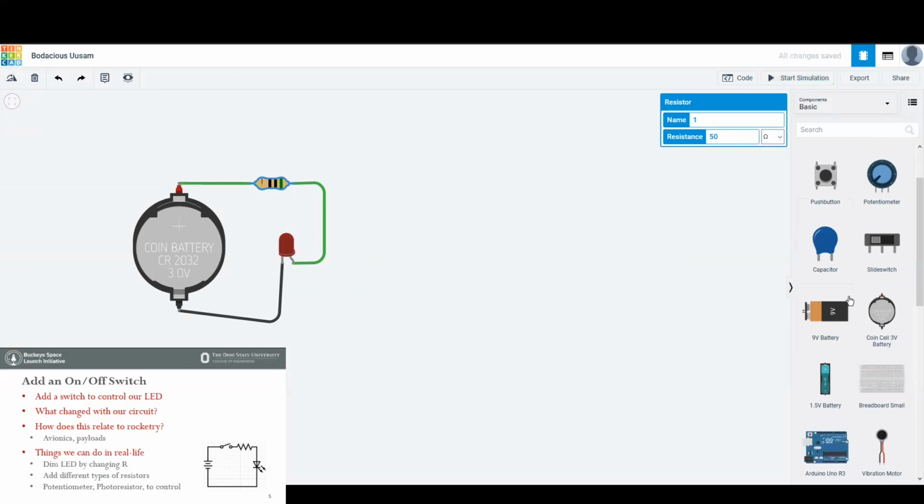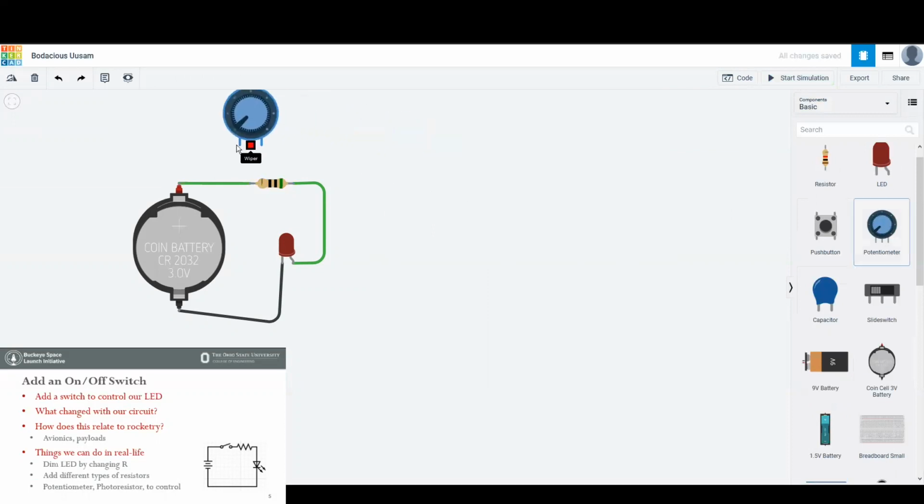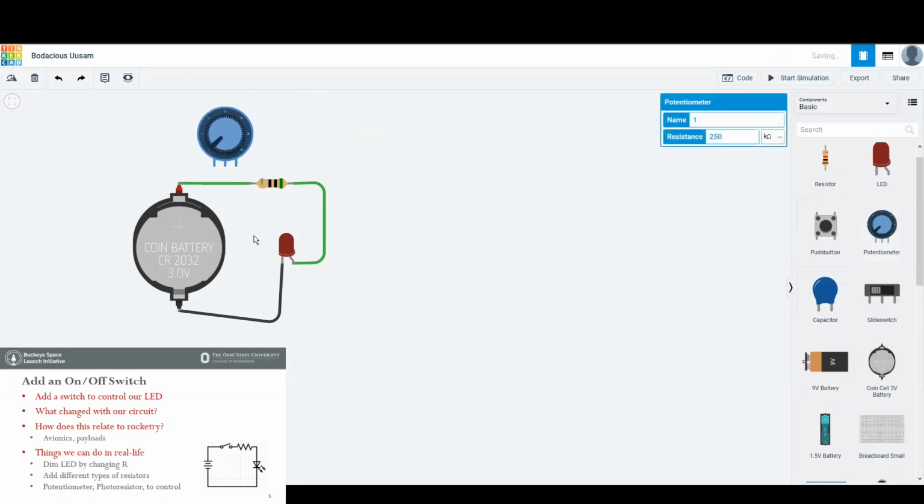So I'm set at the 50. Let me stop. Where's the potentiometer? So the potentiometer, I have it listed there, is like a variable resistor. Before I do this, let's look at our leads: terminal 1, the wiper, and terminal 2. So I can do the wiper and terminal 2, just to choose one. And we'll set this resistance to 5 kilo ohms.